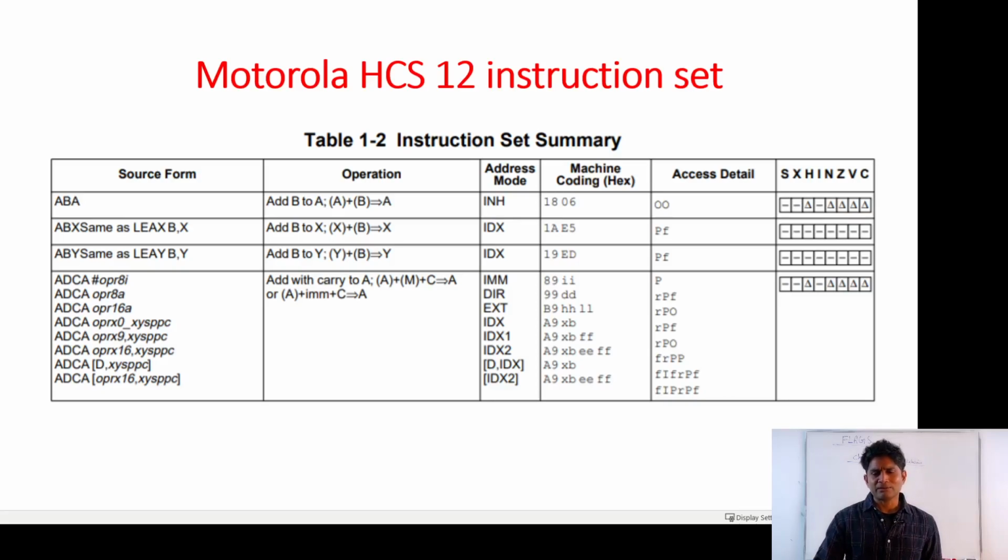Okay, and let's not worry about the addressing mode at this time. Hopefully you'll learn about that in the next version of this class. But you can see that this particular instruction ABA is encoded as a binary code. Of course, here that binary encoding is shown in hexadecimal. That's a 16-bit binary code, and your hexadecimal. The good thing about working with hexadecimal numbers is that it encodes binary numbers in a much more compact fashion.